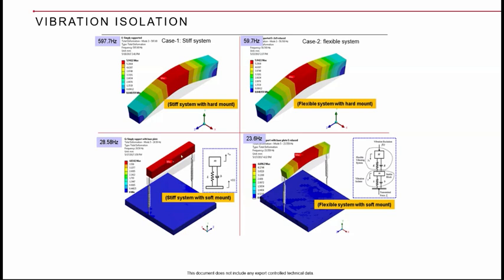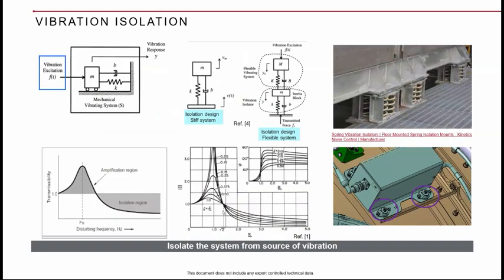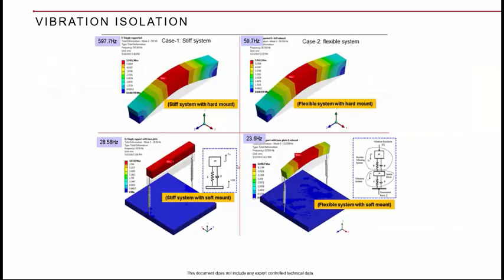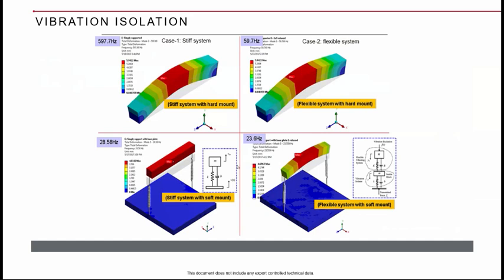Then you see that only the rigid body mode will exist, and that will be below the operating range. So when you are operating the system, this will actually pass in the transition itself, and when the overall system reaches operating, it will be in this zone, whereas we don't have any frequency in that zone. So we are safe. So that is the fundamental behind the isolation system, vibration isolation.